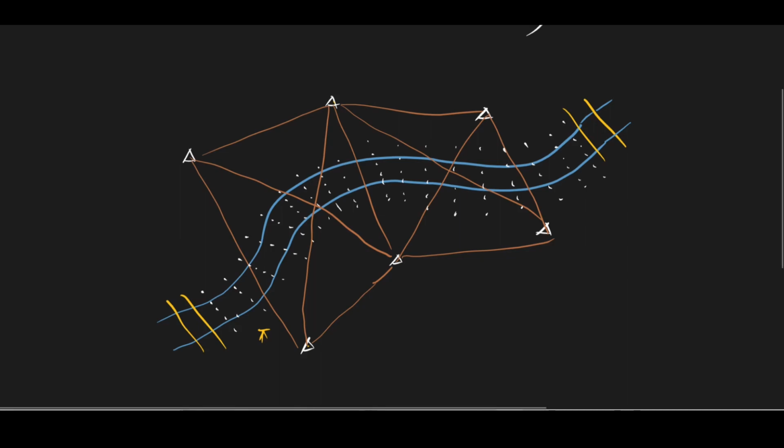And then you transfer, of course, you have a backside right here, and then you transfer stations, right? Transfer stations, observing these cross sections right here, observe them, then you transfer again, and like that. And then you can check your coordinates here. You can check your coordinates. You can adjust for errors of your positioning by referencing to this control point. So that is basically the essence of having control points.